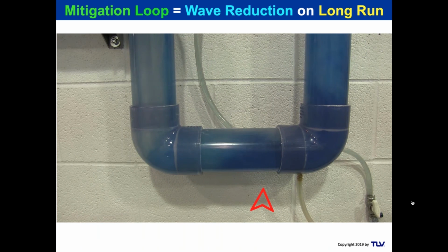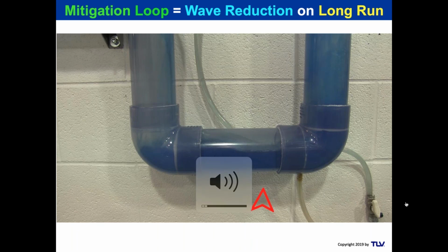So a drop-down loop seal is an idea that you may use. You could always just vent it off and flash it and pump it overhead if you wanted to get rid of a water hammer, which would be safe. And you could always elevate the line. The elevated line is what would be the perfect solution. We have everything with a gravity return. It's just that people don't often have that. It's unfortunate. So we've got to deal with something and mitigate against it in a safe way.